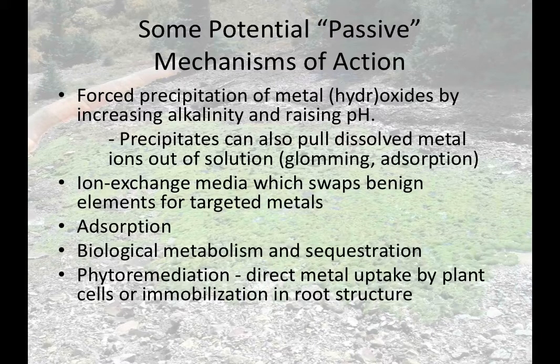So the iron-rich material which we were using is an activated iron ferromanganese where they boil zinc out with an electric arc furnace of slag metals, scrap metals. And what you're left with is an iron that's incredibly fragmented as you boiled the metal that it wanted to be bound to, and it has these activated surfaces. And what we found, and it was actually Adrian Brown at the International Mine Water Association conference in 2013 where I first learned about IRM, the dissolved zinc just gets sucked into that IRM like a sponge. It's a pretty cool one, and I've got a couple charts on that.